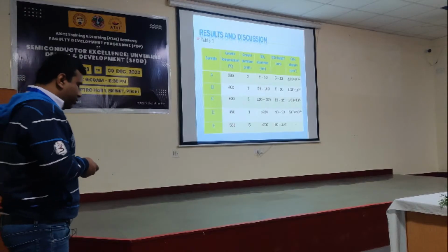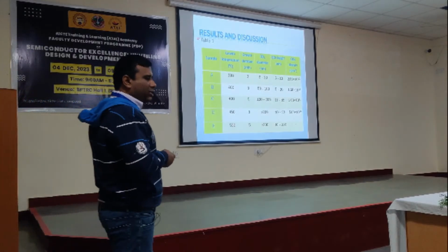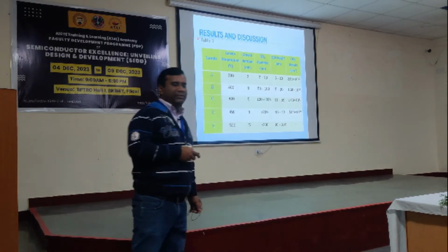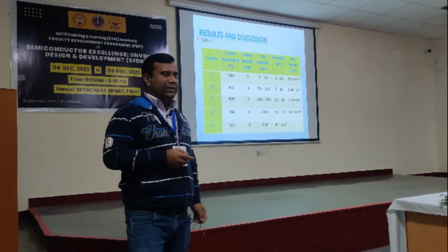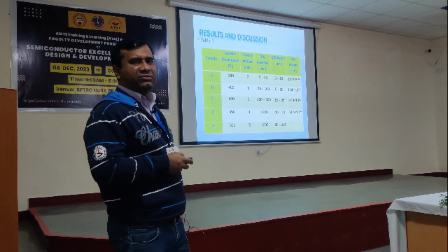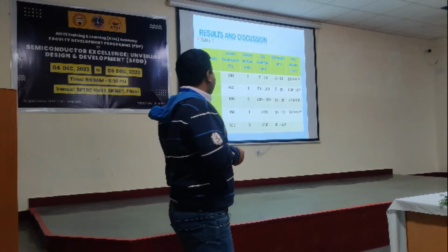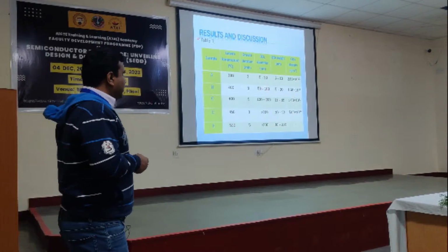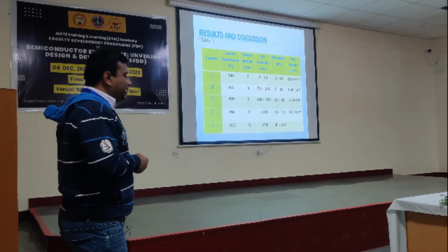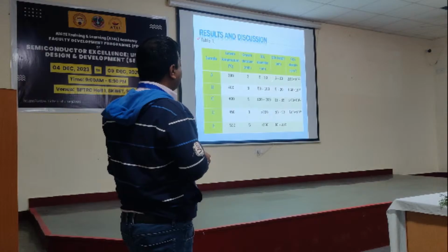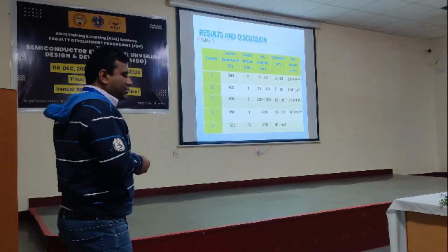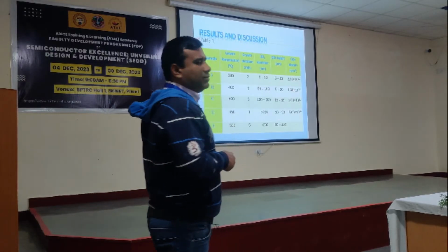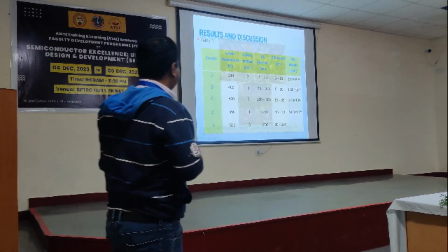Why? Because when you increase the temperature, the precursor molecules, that is indium and methyl, become more mobile. Then a very rapid nucleation process will form. That nucleation process will result in a bigger crystal size. And when the size gets bigger with increasing temperature, many quantum dots agglomerate, and the quantum dot density also decreases.